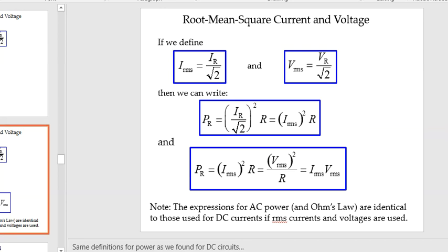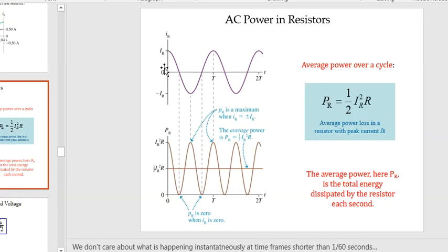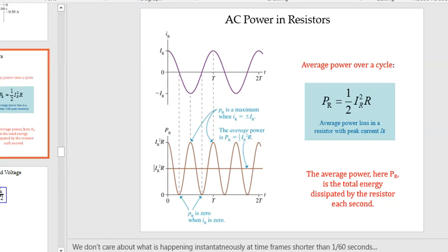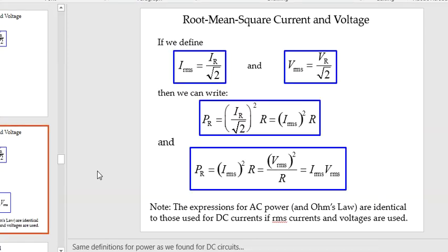So basically what we're doing here is, do you notice how, if you just had this current here and you say, well, okay, what's the average current? It's kind of a nonsensical question, right? Because it's going to be 0. But if we square it and then we take the average of that, and then we take the square root of that, then this is the so-called root mean squared of this quantity. Okay, so that's the meaning of this so-called root mean squared.